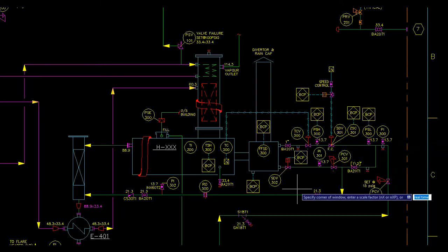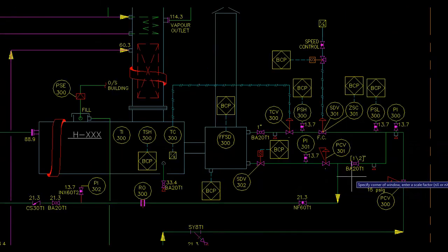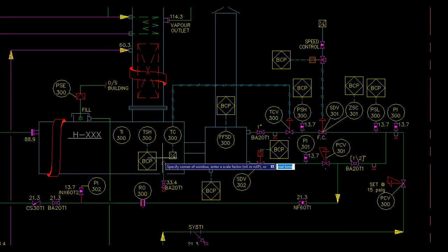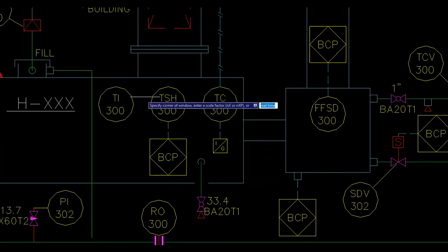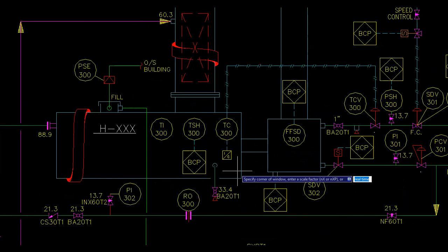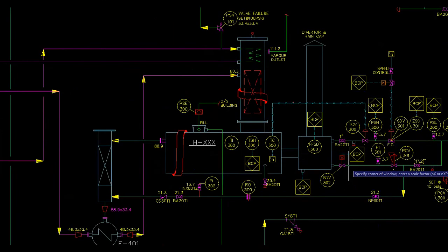The code essentially tells there should be a 2-level shutdown, one driven by gas and the other manual. In addition to the fuel gas train being designed by code, there is a burner management control which has complete management of maintaining temperatures and shutting down as required. This is again a standard for all reboilers.